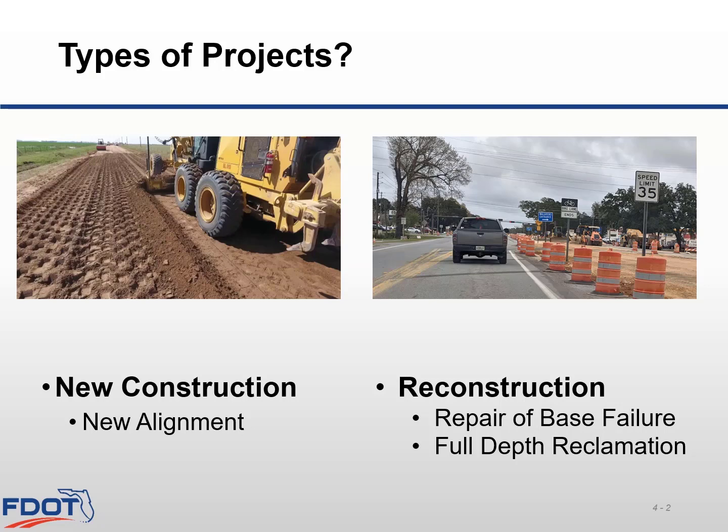It could also be a full depth reclamation project. Essentially, if there is a complete development of a pavement system, or in other words, it involves the construction of new stabilization, base, structural asphalt, and friction course, you'll need to use the design process we'll discuss in this module.